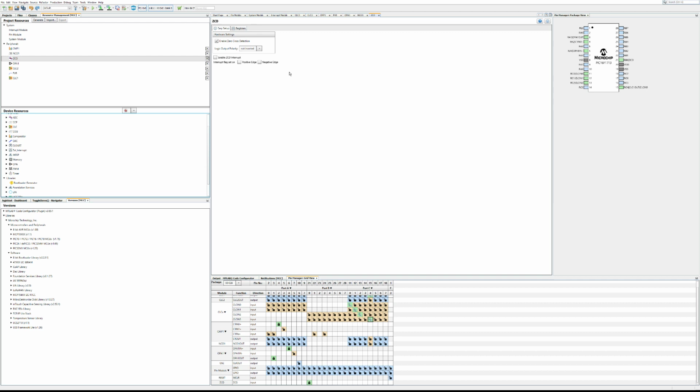So you can put like a 10 meg resistor between mains and this pin and just directly sense mains voltage to find the zero crossing point. Now that's not necessarily advisable because you're breaking isolation, but if this chip is something that's going inside a sealed mains powered unit, then that can be very, very useful and saves you going through a whole bunch of steps with opto isolators and whatnot when you don't actually need isolation anyway.